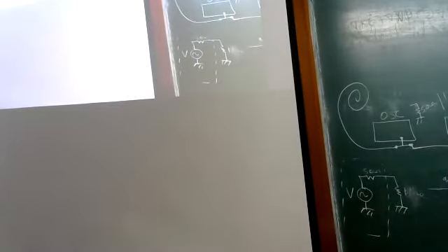Both the oscilloscope and the function generator use a different connector standard, which is this one. It's called BNC. I'm using a BNC to SMA adapter to go between these two things. These two different series, BNC and SMA, basically differ in size. BNC is bigger in size, larger cable, larger connector, which also means that it doesn't work to very high frequencies.